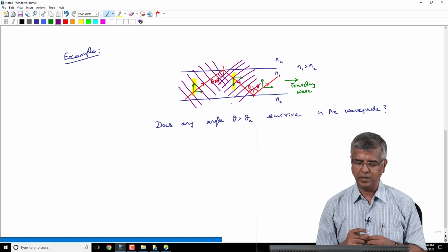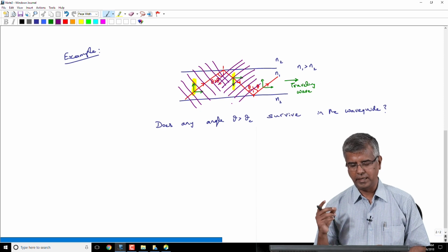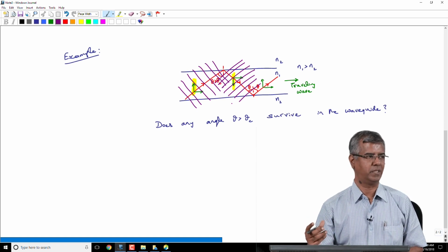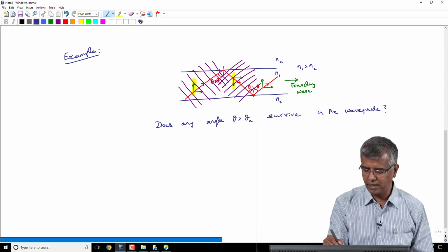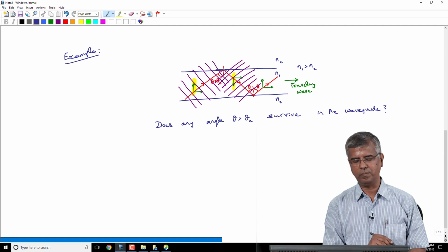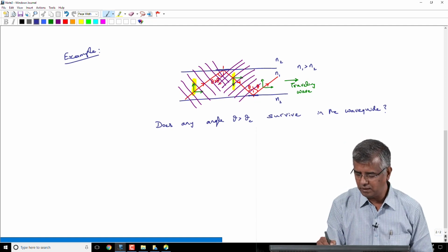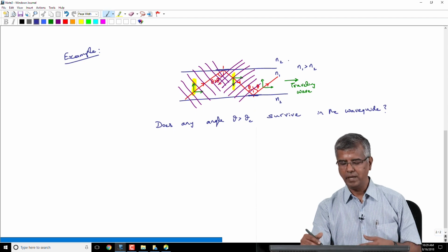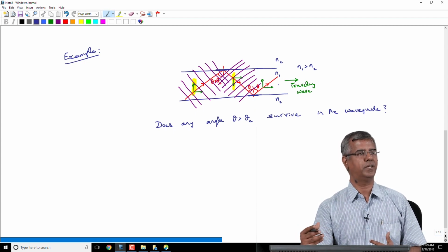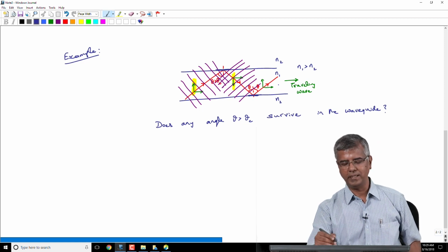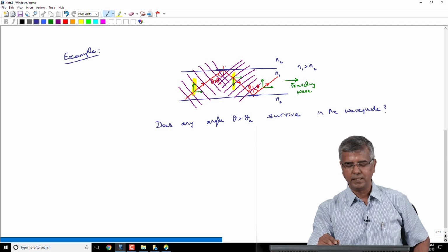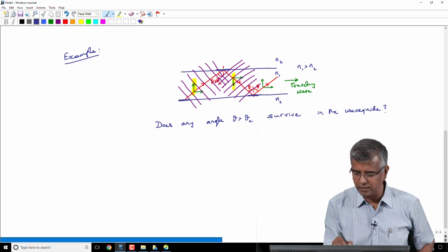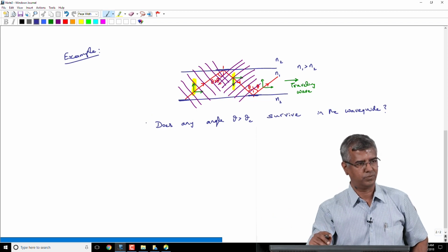And the key point here is, for an electromagnetic wave to be supported in this structure, it has to satisfy Maxwell's equations. And Maxwell's equations say that I have to satisfy certain conditions at this boundary, but that same condition would have to be satisfied at this boundary as well, because the angle of incidence is the same, and the interfaces are the same, right. So, whatever boundary condition I am satisfying at this boundary is the same boundary condition that I will have to satisfy here, every time it goes through the bounce. Okay.